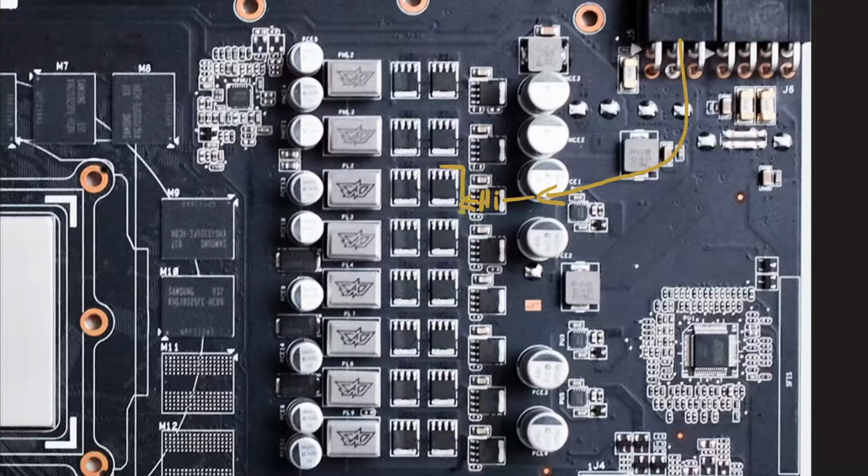So the low side MOSFETs, there's no 12 volts power going through them like through the high side MOSFETs. What is going through the low side MOSFETs will be the output voltage of the VRM, so say 1.2 volts. And 1.2 volts in comparison to 12 volts will be 10 times the current. So those have to handle 10 times the current, and 10 times the current means the RDS on resistance has 10 times the effect of how much heat it will produce. So that's also why there are 2 sometimes.